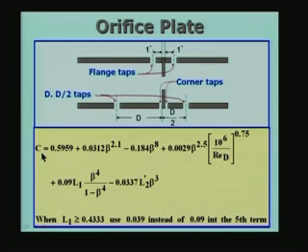Normally what we do in the case of an orifice plate is we can start with the value of C equal to 0.6 as a starting value, because we will see later that the value of C is close to that value. Then, after evaluating the velocity from the pressure drop data, you come back here, calculate the Reynolds number based on the evaluated velocity, and then correct the C value by using this equation, the Stolz equation. Maybe one or two iterations will be sufficient for this purpose.